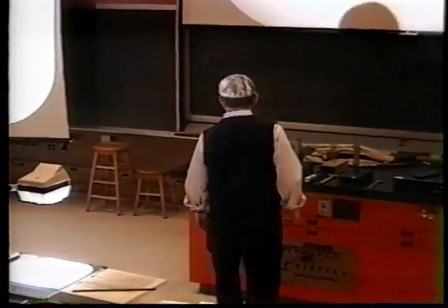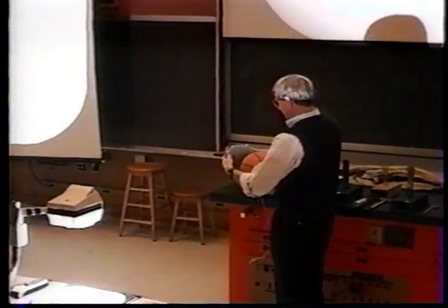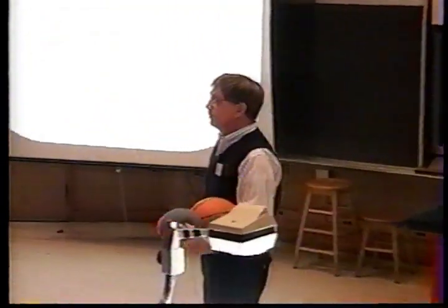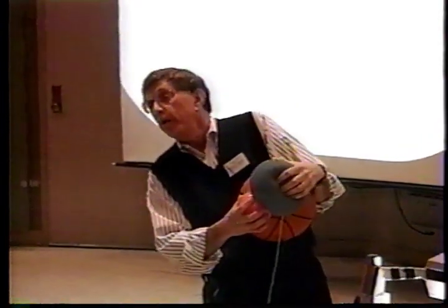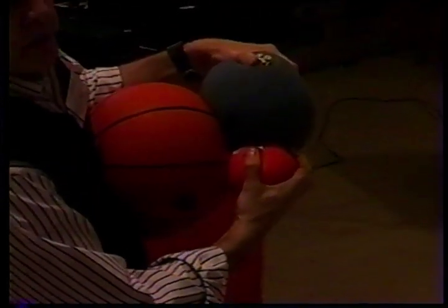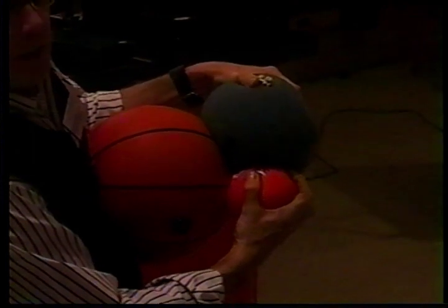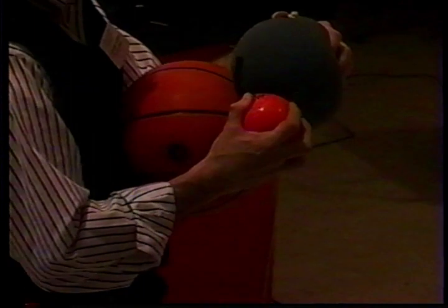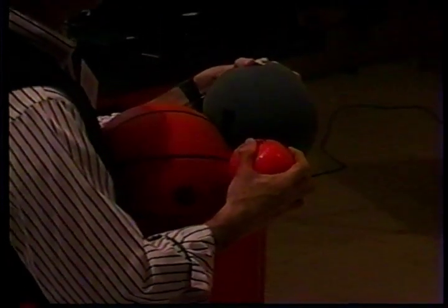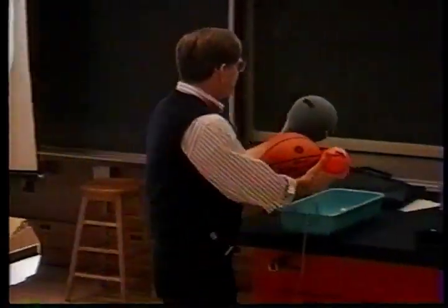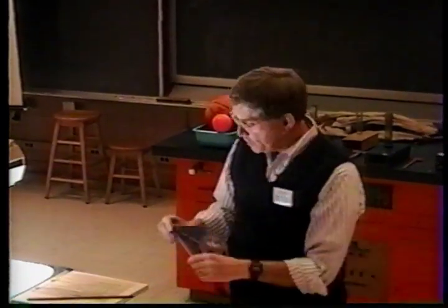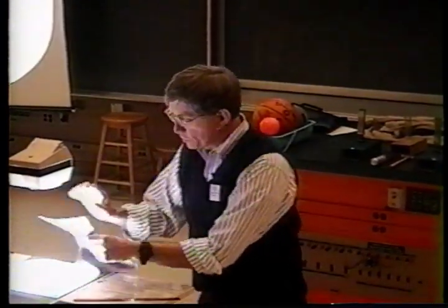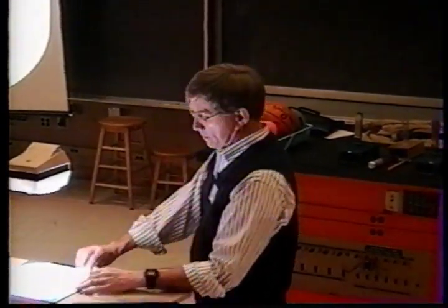Because if you have 3 satellites, no matter whether the actual ranges or the pseudo ranges are used, they will intersect at actually 2 points somewhere. But it'll be the wrong 2 points. By using 4 satellites, you'll have this 3 times, and then by adjusting the delta t, which you don't know, you can bring the intersection points into coincidence. So 4 satellites are required, and when you get the right delta t, you achieve what's shown in this slide here, and I have to turn some lights out to make it visible.